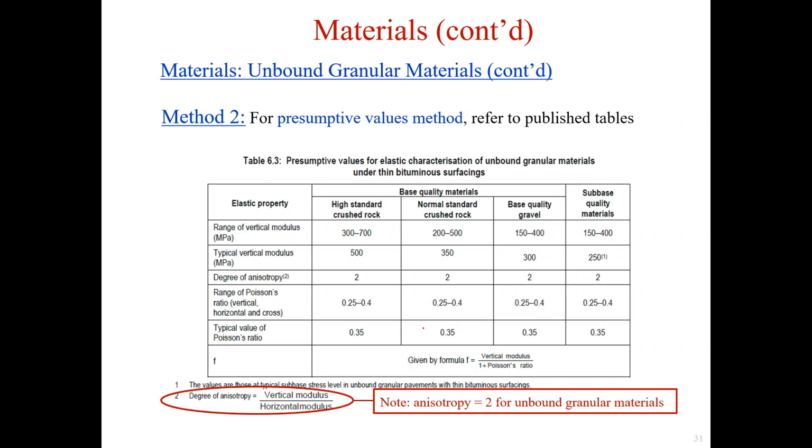Normal standard crushed rocks are those commonly used by road authorities. Because the moduli of unbound granular materials are stress dependent and dependent on moisture and compaction levels in the road bed, caution must be exercised in applying this empirical data. This table may be used as a guide when assigning maximum values to granular materials and sealing bituminous surfacings when other more reliable information is unavailable.